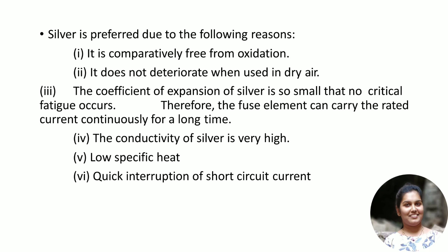So these are the points which are to be kept in mind while selecting a particular element as fusing element. Okay, you can choose depending upon your cost constraints, depending upon the environmental conditions, oxidation process, and also melting conditions, and all these points put together will decide what kind of fuse should be taken for your particular application.